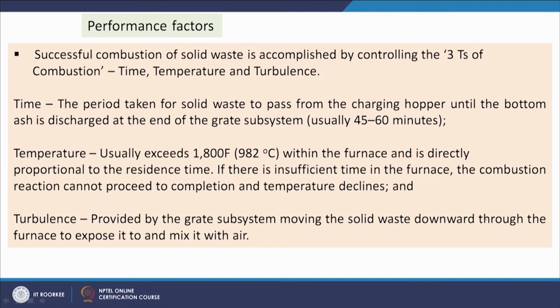And the performance of the combustion reactions depends upon 3 T's, that is time, temperature and turbulence. So, when we are interested to heat it and combust it, we need to provide certain time, so that complete conversion can take place within that time as per the rate constant of the reactions, or as per the rate of the reactions. And then temperature, certain temperature is required for firing itself and to maintain the rate of reactions. And then turbulence is needed, because turbulence will give us more chance of the mixing of the air and the solid particles.